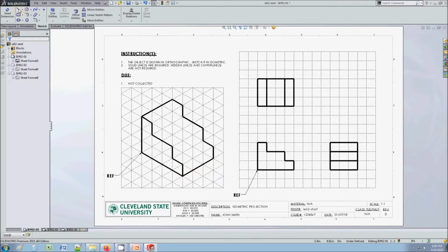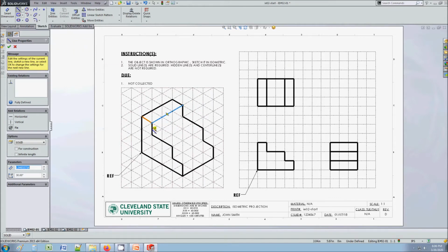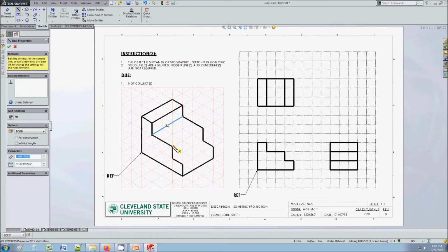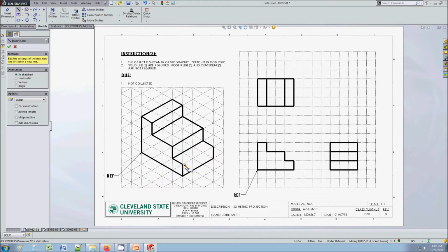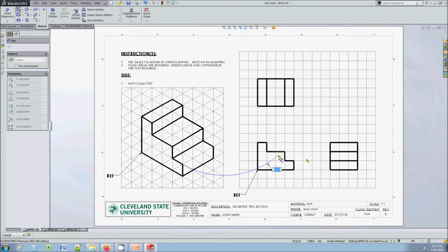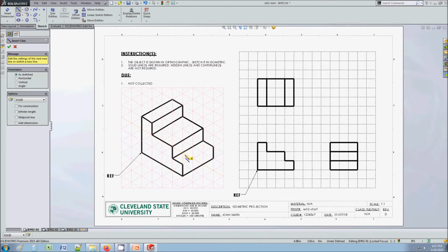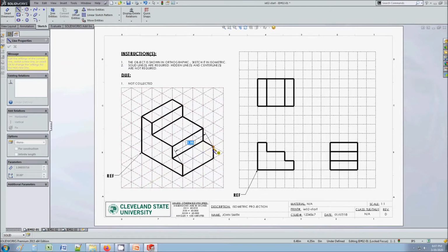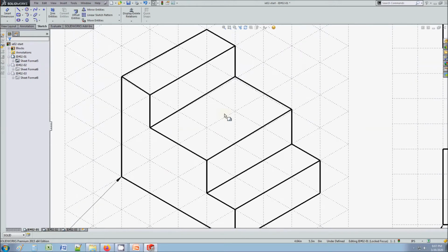You can snap. Whenever you see that yellow line, that yellow box, that means you're snapping. Okay. At every node, you got to ask yourself, which direction am I going to go? See, I can either go up, to the side, down, up. You will always be given enough clues from the orthographic views to know which direction to go. So you got to double check. You got to traverse this. You got to say, all right, I'm here, which means I'm here, then I go here, and then I go down there. You got to be able to traverse this schematic.